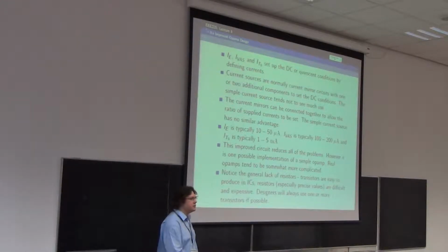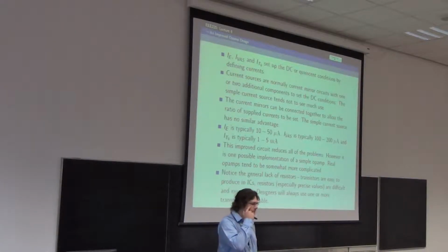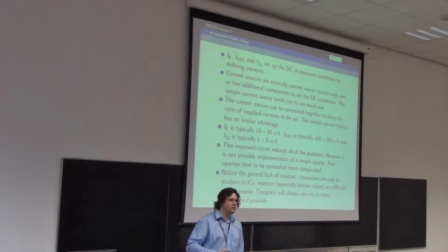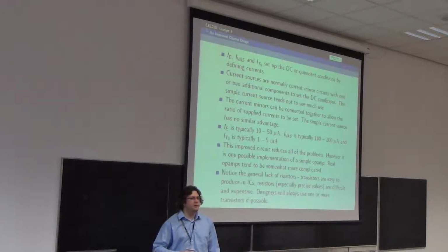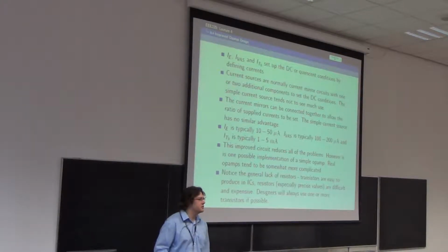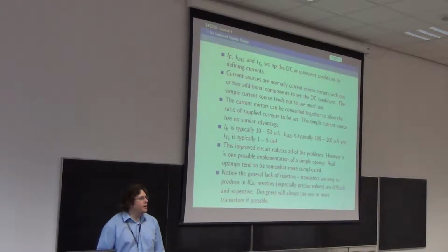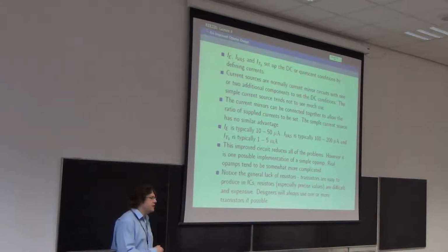And you still need a resistor, and you need to fabricate some sort of biasing arrangement, which could be a potential divider, or you could use a Zener diode and a resistor, or you could use a couple of diodes that are biased, and there are lots of options. You can just Google current source, I'm sure loads and loads will come up. Actually, they don't tend to turn up very much, because they have some problems.